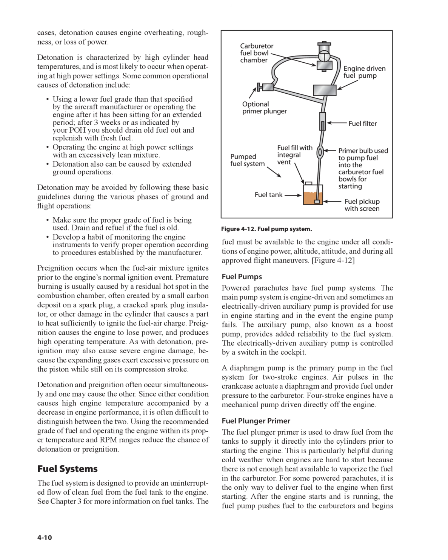Make sure the proper grade of fuel is being used. Drain and refuel if the fuel is old. Develop a habit of monitoring the engine instruments to verify proper operation according to procedures established by the manufacturer.